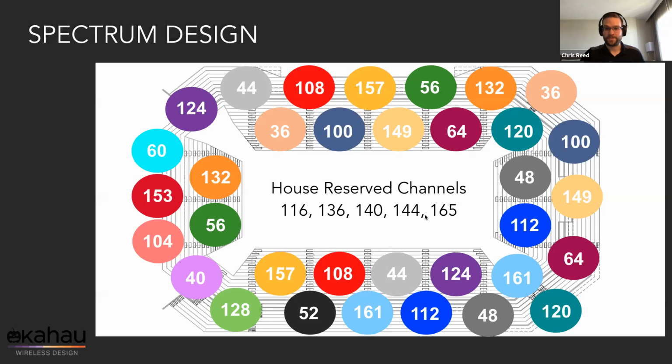Or are they doing wireless video delivery in some of the channels that you're looking at, and it's not adhering to the Wi-Fi standard? It's just an analog video stream that is just taking up the spectrum. So you may not want to use that channel in your plan.